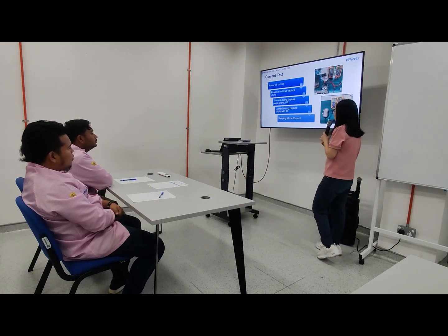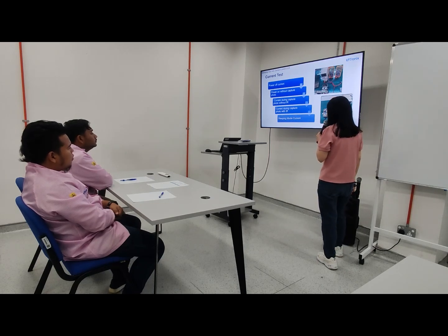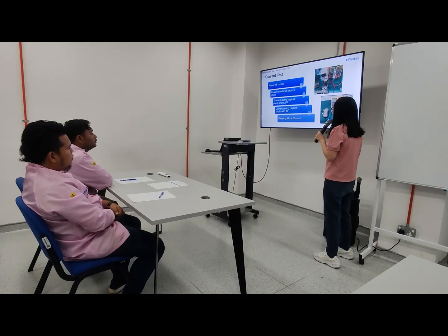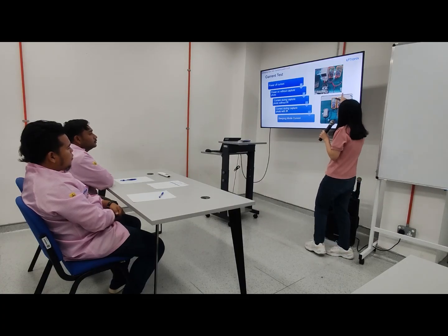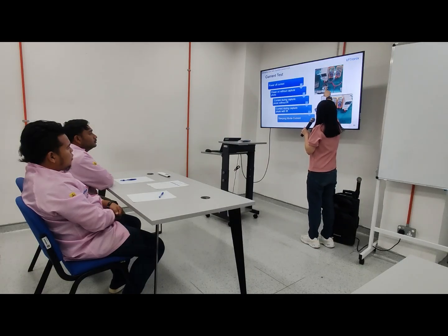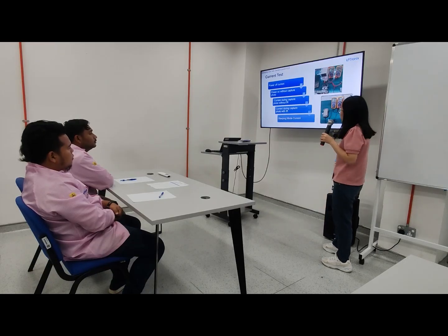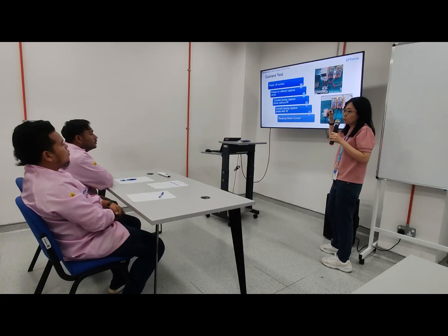Okay. The fourth one is the current during capture photo with IR. With IR means we will cover the CDS sensor with black coat. Then we measure the current. Okay? Fifth one, sleep mode.